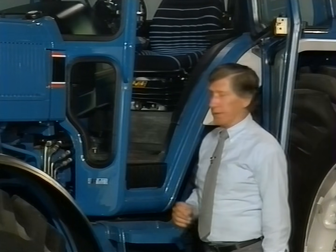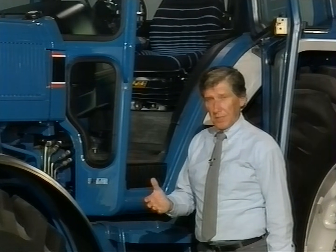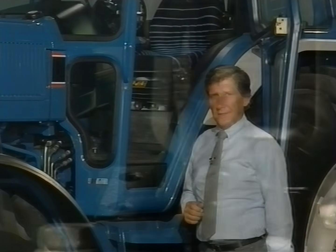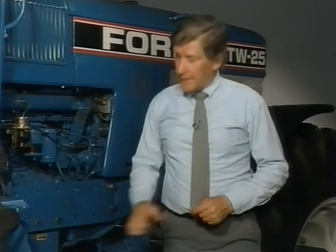The handbrake warning switch is located beneath the handbrake assembly. This is a magnetic switch that opens with the handbrake lever lowered and closes when the lever is engaged. It accomplishes this through a metal tab that prevents the switch from closing when it is positioned between the magnet and the switch contacts. While we're in the area, let's take a look at the input for charging system voltage.